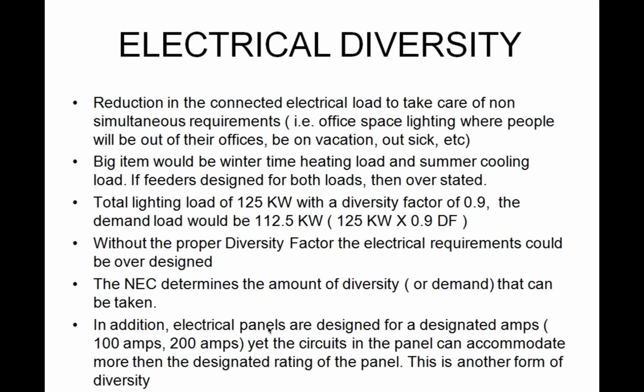If you calculate that way, you're probably over-designing your systems. Chances are there will be spaces that aren't used, someone's on vacation or out sick, and not every computer is in use at all times. So usually a diversity factor of 0.9 is used to determine what the peak load would really be.